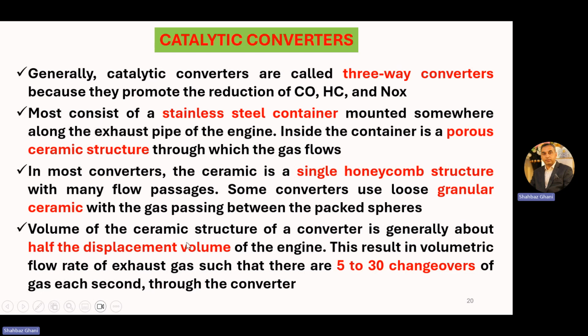So if the total volume of the engine is 3 liters, the ceramic structure volume should be 1.5 liters. This results in a volumetric flow rate of the exhaust gases such that there are 5 to 30 changeovers of gases each second through the converter.